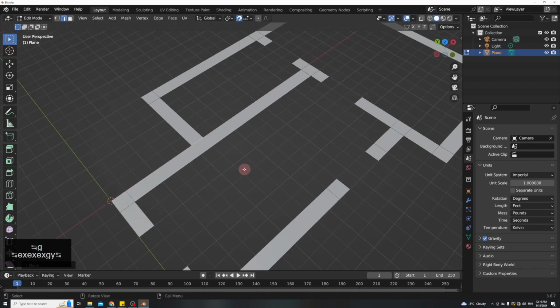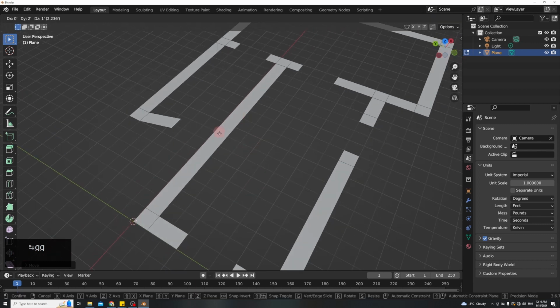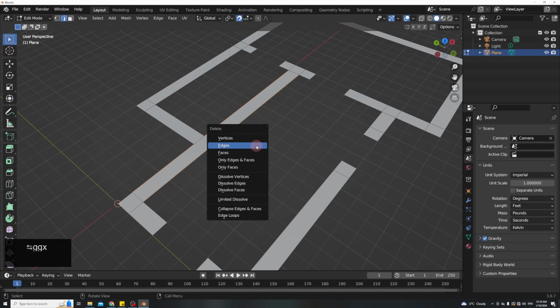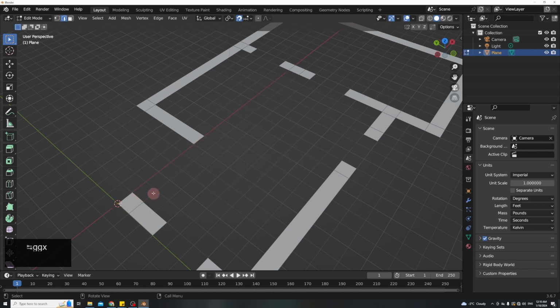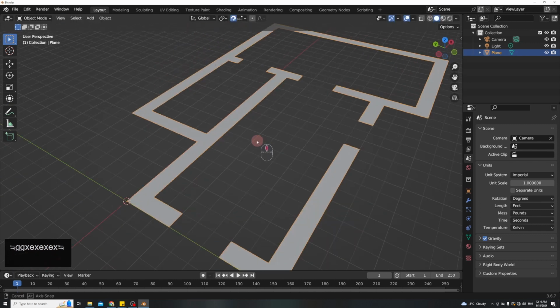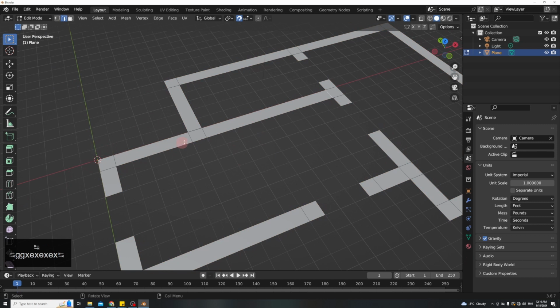So to solve that problem, well, there's a few different ways, but the best way to make sure your geometry is clean is to actually delete this entire wall. Then I extrude up this way, up this way, up this way. Now I've created a new joint.